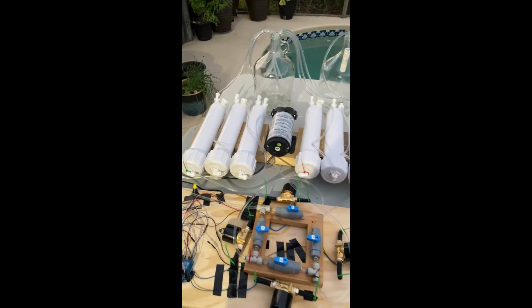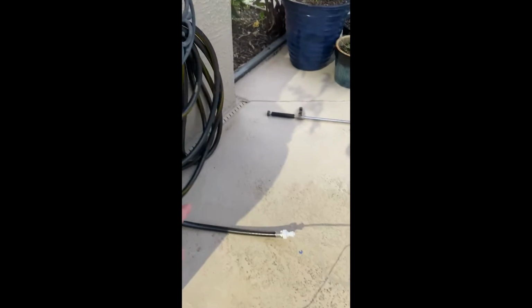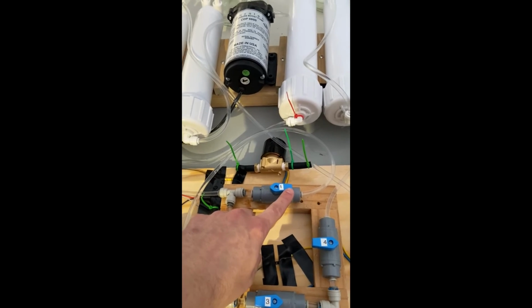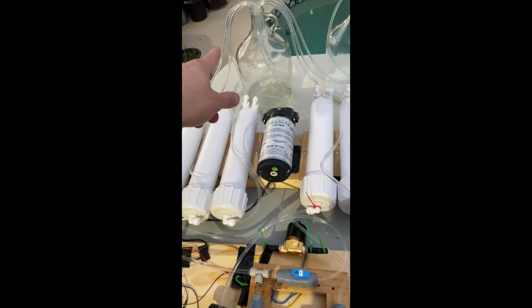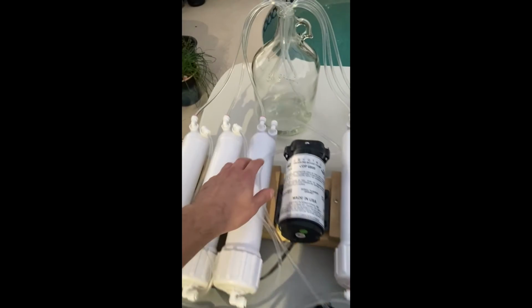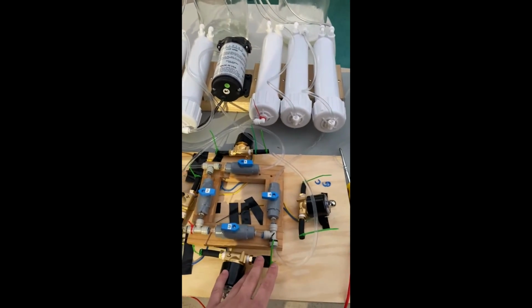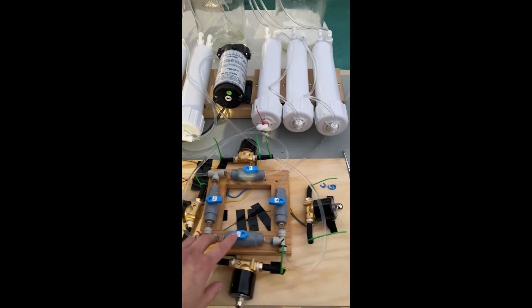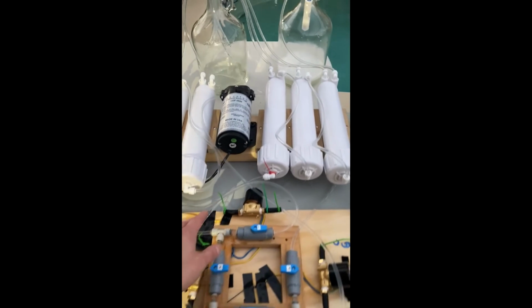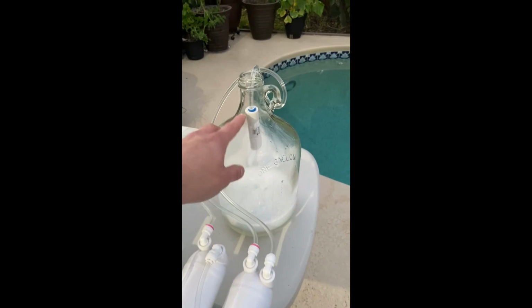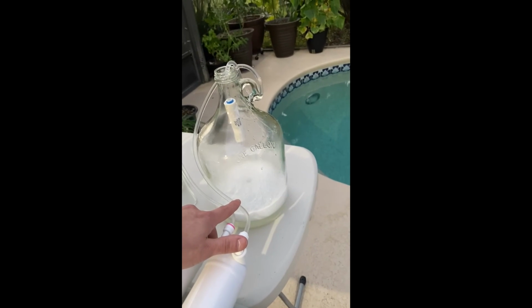Here is the system in operation. Water comes from the garden hose into the feed water. It passes through the open valve number 1 and is fed into Array 1. Permeate is produced. The reject concentrate water from Array 1 is fed into the boost pump, which increases the pressure, feeds it back into the valve manifold. Valve 4 is closed. Water is redirected through valve 3 and into the intake of Array 2, again, permeate is produced. Finally, the final concentrate stream goes into a flow restrictor and into this holding vessel.